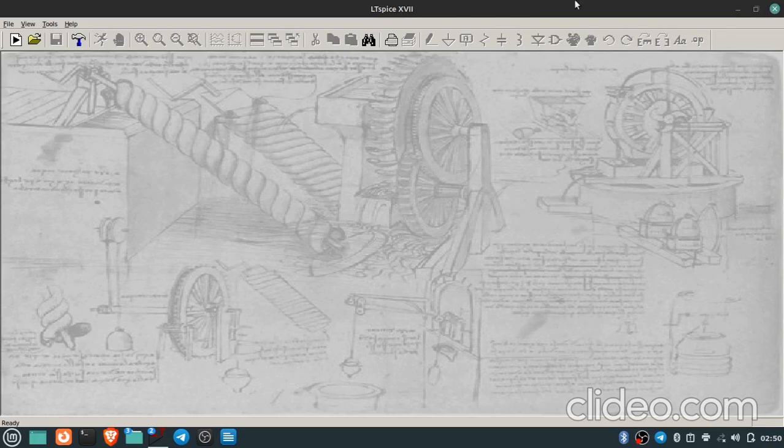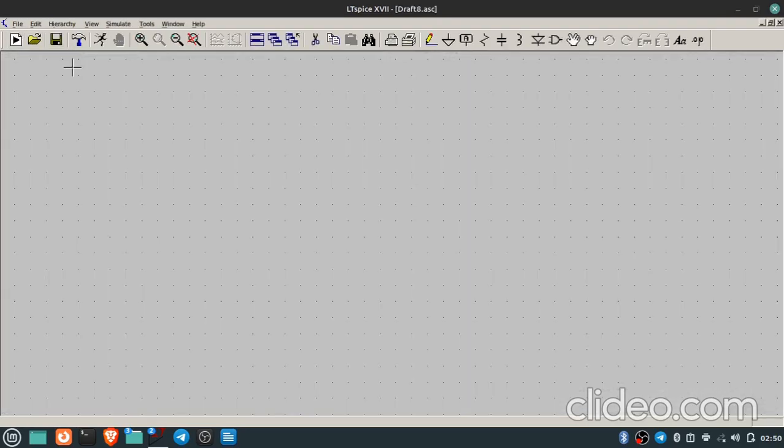First, start LTspice, and then to start a new schematic, you can just press this new schematic button or just press Ctrl M. We're gonna do a simple RC circuit in this session. So first, for a resistor, click R. Then to rotate it, click Ctrl R. Okay. Then we need a capacitor for this. We're gonna click C. We got a capacitor. We're gonna place it here.